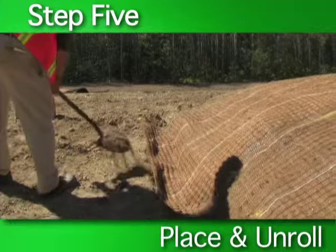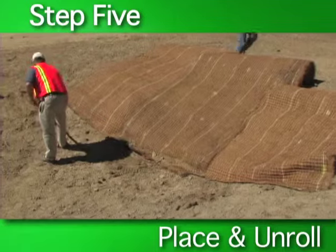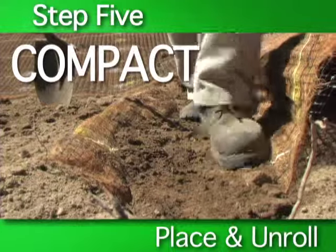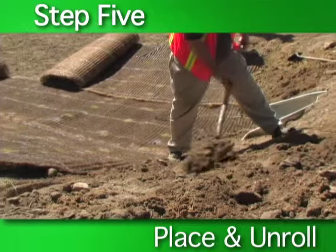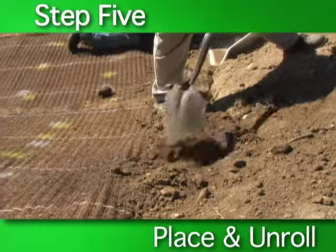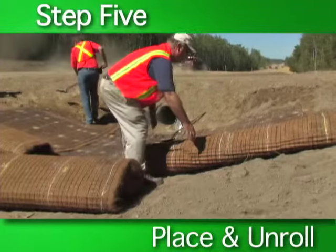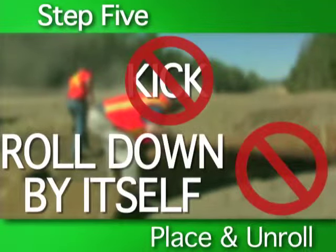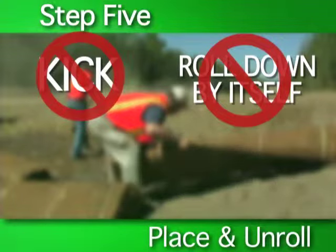With the RECP now secured to the bottom of the trench, backfill and compact the soil, being sure to place seed over the compacted soil. The next step is to fold the product over the compacted anchor trench, finishing off and leveling the beginning of the RECP. Unroll the RECP by walking it down the channel, guiding the product as you go. You do not want to kick or let the product roll down unaided, as this can cause product damage or pull the product out of its anchor trench. Let's now move on to Step 6.